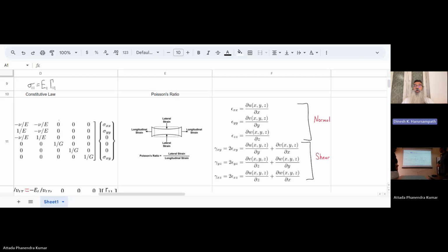So it would rather go under an equation meant for the constitutive law, which relates the stress to the strain, because you're applying stress in one direction, because of which sigma 11 is caused, and in turn also strain 22 is caused, and you're looking at the ratio of that, which is purely a material property, and all purely material properties come under the constitutive law.